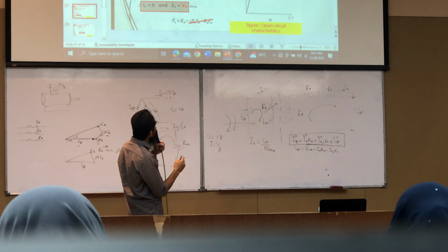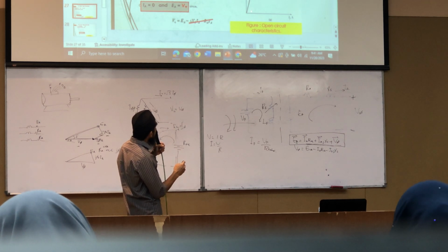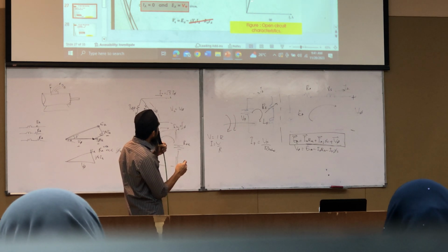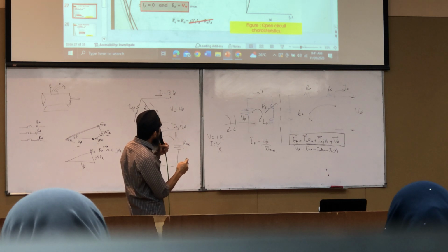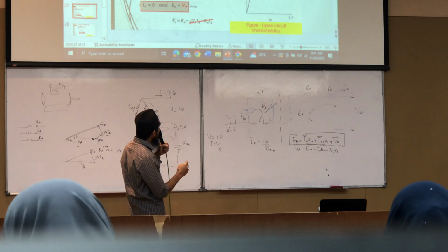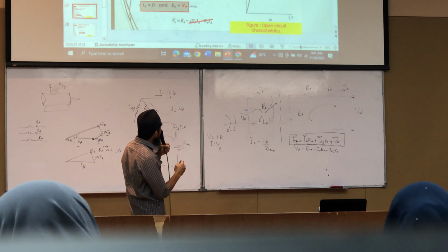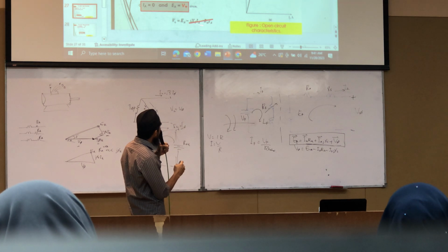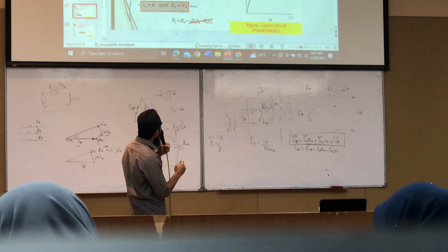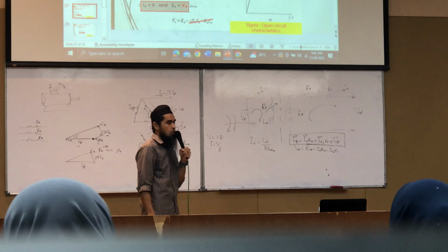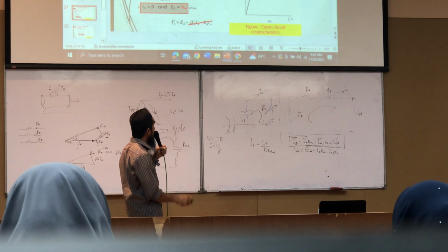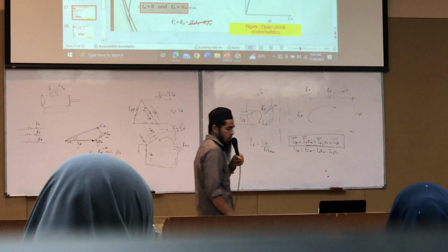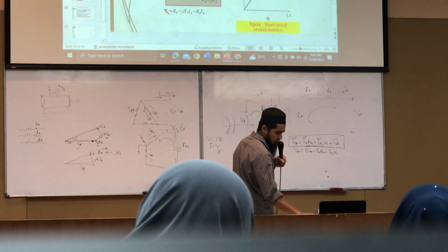Open circuit test. So we increase the field current, measure the voltage, increase, measure, then we plot the graph. So this is what you have to do inside your lab. There is no component for RA, IA and jXS because at this time IA is considered as zero, open circuit. No current is delivered to the load because we are not connecting to any load. So that's the first curve you have to generate.